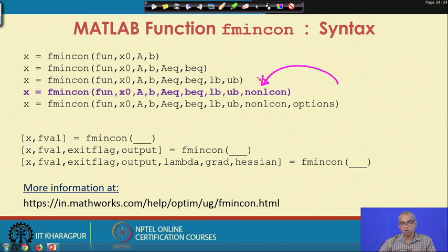I have given the name nonlcon; you can give whatever name you want. The idea is that you have to supply a function where you will write down the nonlinear constraints associated with the optimization problem.